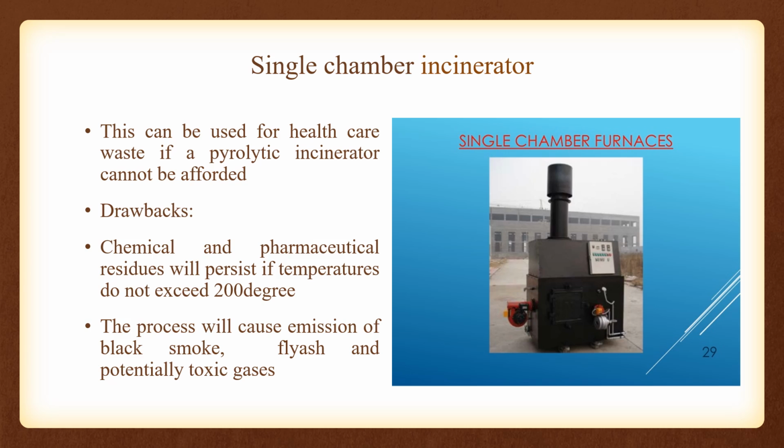It has its own drawbacks. Chemical and pharmaceutical residues will persist if temperatures do not exceed 200 degrees centigrade, and the process will also cause emission of black smoke, fly ash and potentially toxic gases. Exhaust gas cleaning is not practical, and it can cause air pollution. These are the drawbacks of single chamber furnaces, that is, single chamber incinerators.